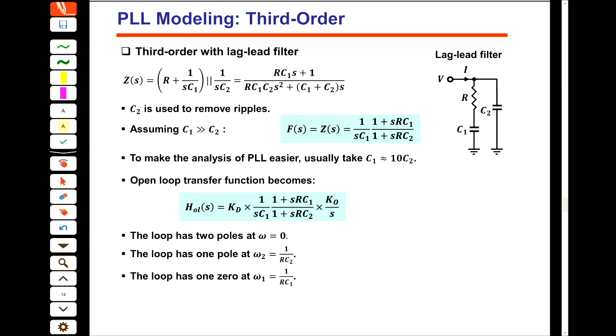Yes, when we are taking assumptions, you need to write down the assumptions taken, for example, a KCL here, a KCL here, and a KVL here, and then find the answer. But we know that beta DC is greater than beta AC. We know that, right? Yes, we know. So this is my beta AC, this is my beta AC.